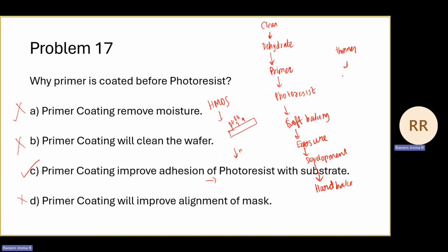If you look at e-beam photoresist, in addition to having a different way of exposure, the resists are also very thin. And even in optical lithography, there is a wide range of photoresists with different thicknesses. With photoresists having lower thickness, you can have smaller size features.